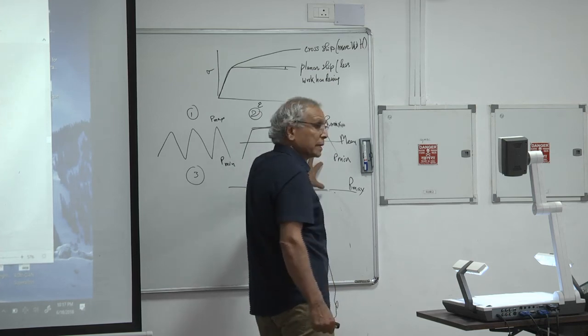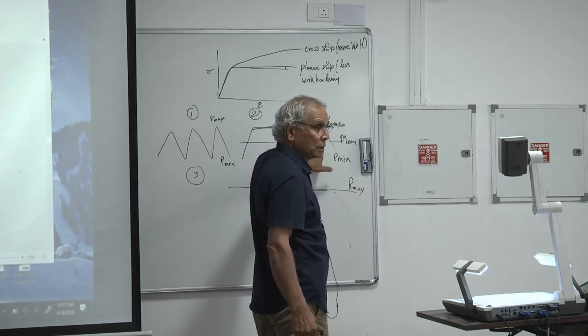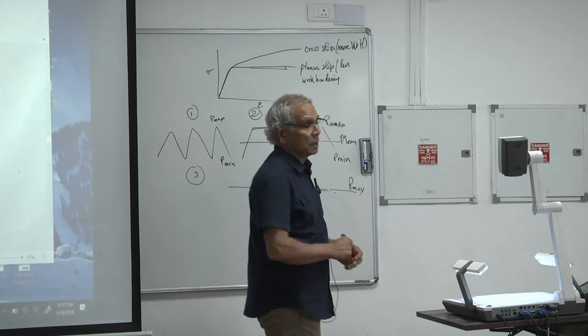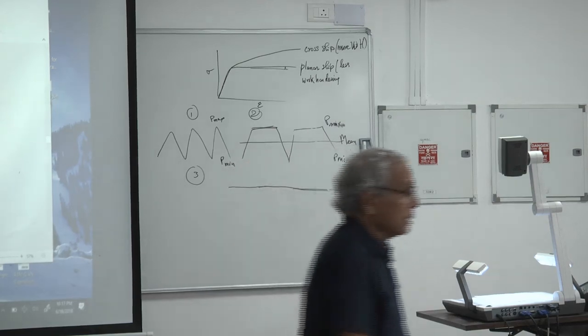You can shift the whole thing down, along with this. So you can have less positive load or more positive load. That will affect the fatigue resistance. As the mean stress increases, as the mean becomes more and more positive, it will be more static, more of a dead load test.